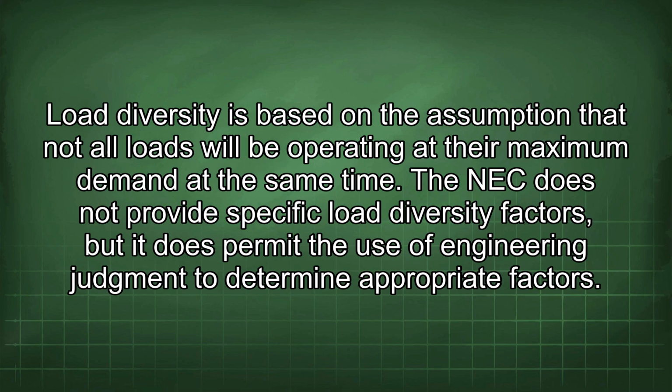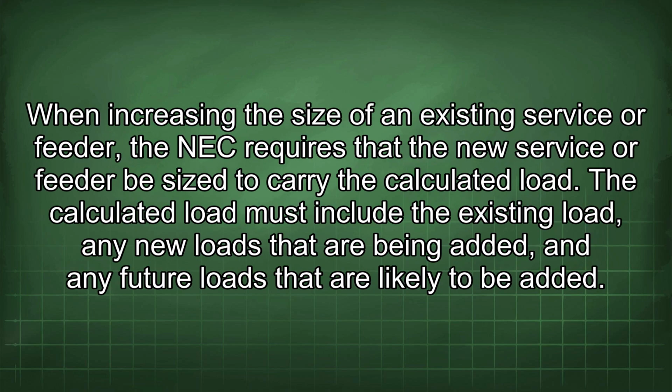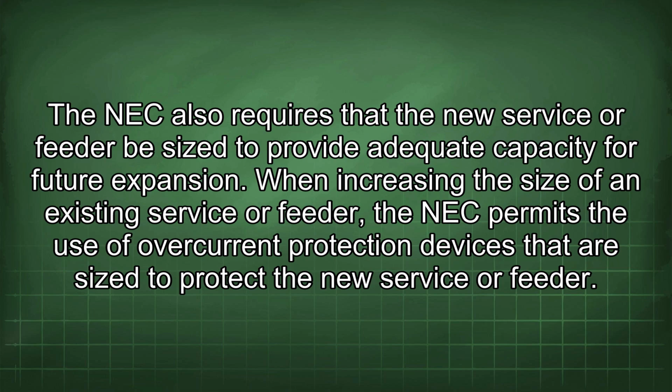When increasing the size of an existing service or feeder, the NEC requires that the new service or feeder be sized to carry the calculated load. The calculated load must include the existing load, any new loads that are being added, and any future loads that are likely to be added. The NEC also requires that the new service or feeder be sized to provide adequate capacity for future expansion.